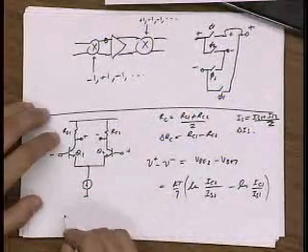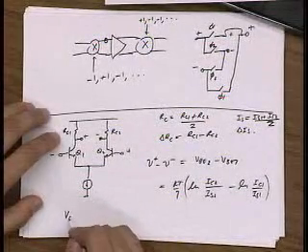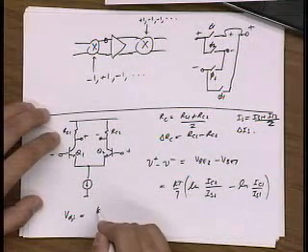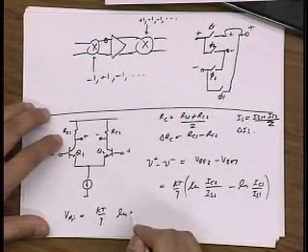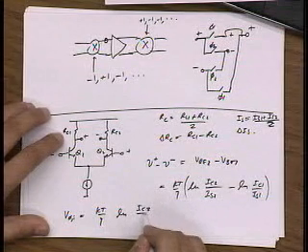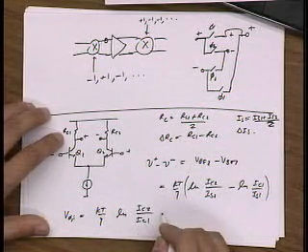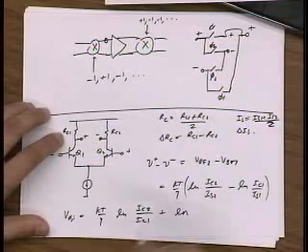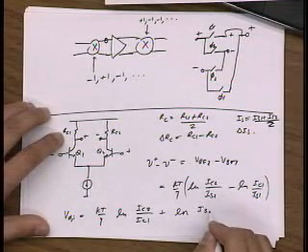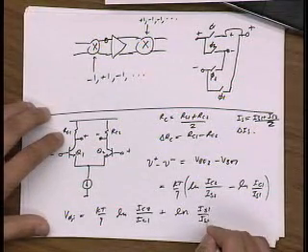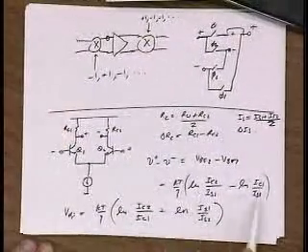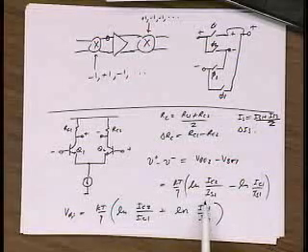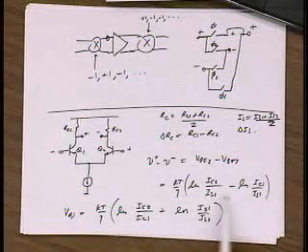And therefore I could say the differential input is kT/q [log IC2/IC1 + log IS1/IS2]. Right, so log of the product is the sum of the logs, right? So I take the product here and then I write it as a sum again.